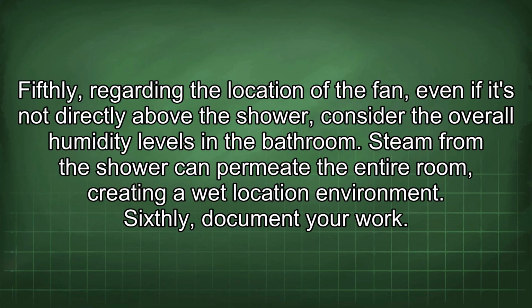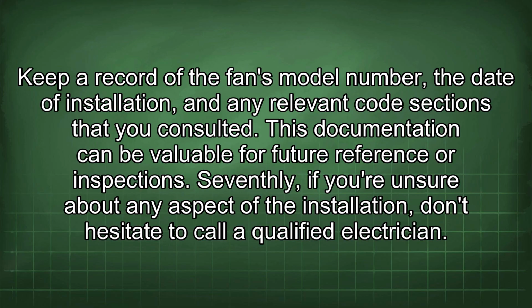Sixthly, document your work. Keep a record of the fan's model number, the date of installation, and any relevant code sections that you consulted. This documentation can be valuable for future reference or inspections.